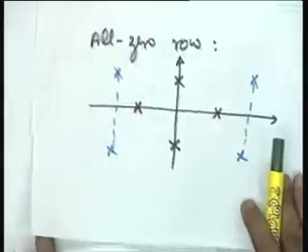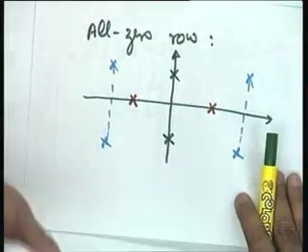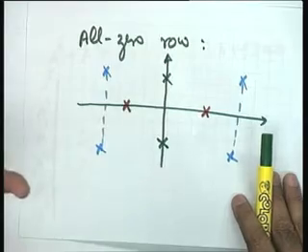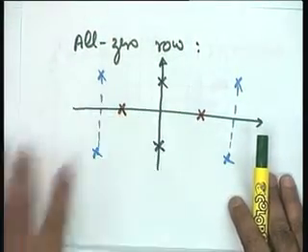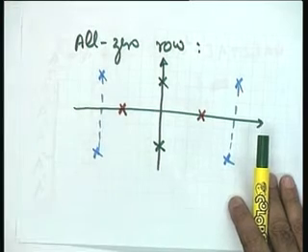So it means an S0 all 0 row will not occur, and if it occurs, it is not related to this particular situation. You can go for the formulation of the Routh array as per the earlier conclusion.